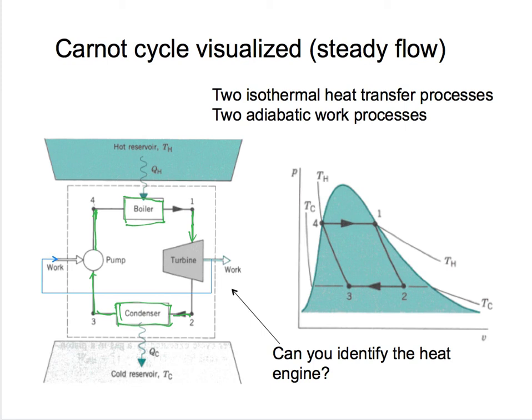All right, if we were to realize this heat engine process using water as the working fluid, this is how we may realize that. Then this will happen all inside the saturation dome, so that we can utilize the isothermal heat addition and isothermal heat rejection process. The isothermal heat addition would happen when the water is in the form of a saturated liquid and saturated vapor. So you begin from a saturated liquid, and then you add heat to the working fluid. Its temperature will not increase. You can add heat to such a working fluid without increasing its temperature.